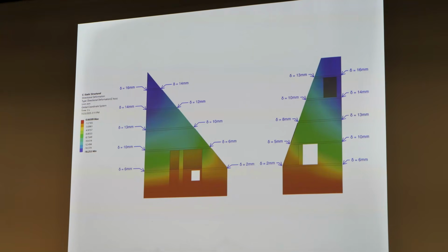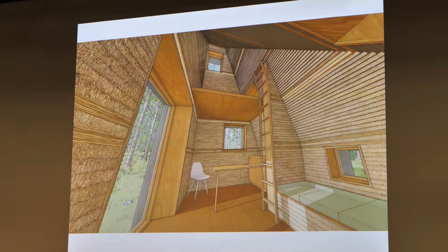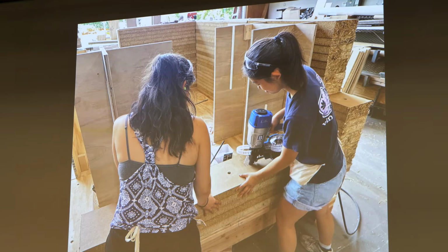Testing to make sure where the compressions are going to be, what the creep will be, as well as looking at the kind of interior environment for this experimental demonstration of the performance capacities of an all-straw building. Straw on the outside, straw on the inside. It's put together with wood pneumatic nails that are powered in so that if you have to take it apart, you don't have to worry about having steel in there. There's some steel rods that go through to tie it together, but it's primarily put together with the friction of the lignin, which is basically the glue of the wood cell as it goes through the straw.